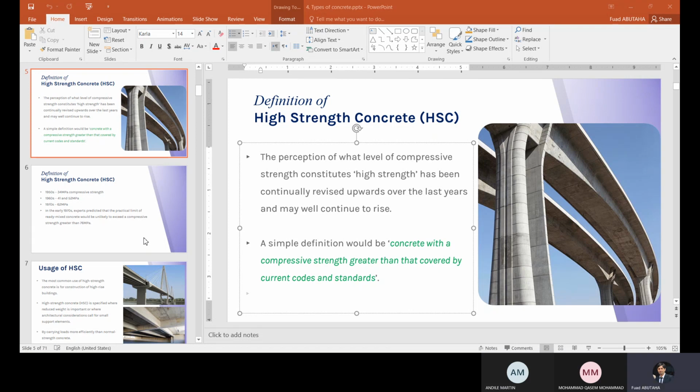This is in general. Just apply this to any concrete materials: sand, aggregate, coarse aggregate, stone, or even the binders. If you want to use cement and you have another filler material like silica fume, the smaller the particle size, the higher the strength, always.